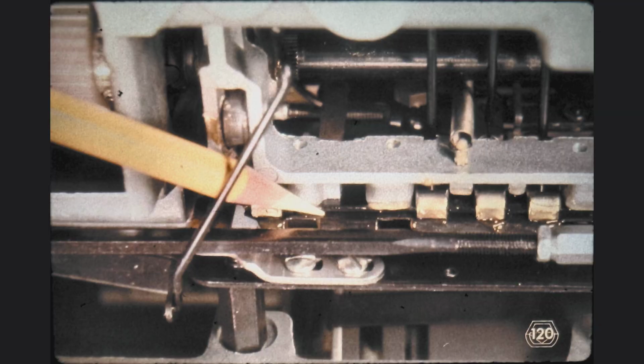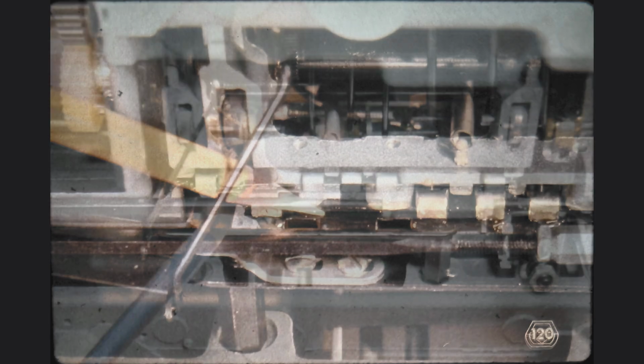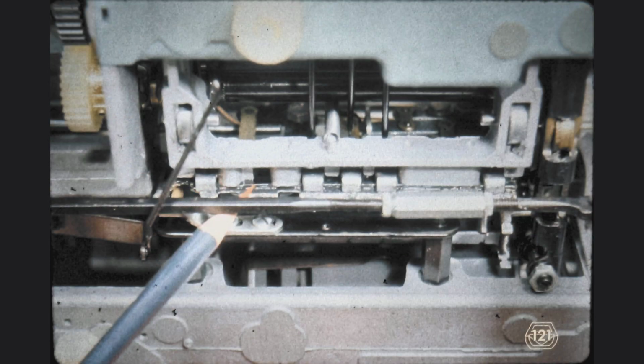On late-style latch bails, or cam followers, the rearward motion of the selector latches is limited by the indicated plate. This plate is positioned immediately to the rear of the latch bail or cam follower. No matter what style of latch bail your machine has, we want full engagement of the selector latch under the indicated latch bail or cam follower.